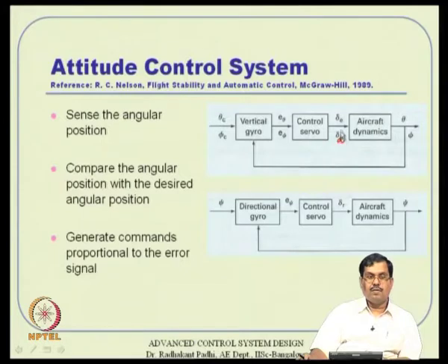So, then it generates the actuator commands. Then it will pass through the actuator system, and what you see as servo control and all are actuators in the loop. Ultimately this comes out of the actuator, the output of the actuator, and goes to the aircraft and excites the system. So, it is not very much different from what you have studied in feedback control. You have a set point regulation problem: you have got some command, there is the actual value, and there is an error signal. Based on this error signal, if I just multiply with a gain, I get P control. If I do algebraic manipulation like differentiation or integration, then I can realize a PID controller. Okay. So, that is how it operates.